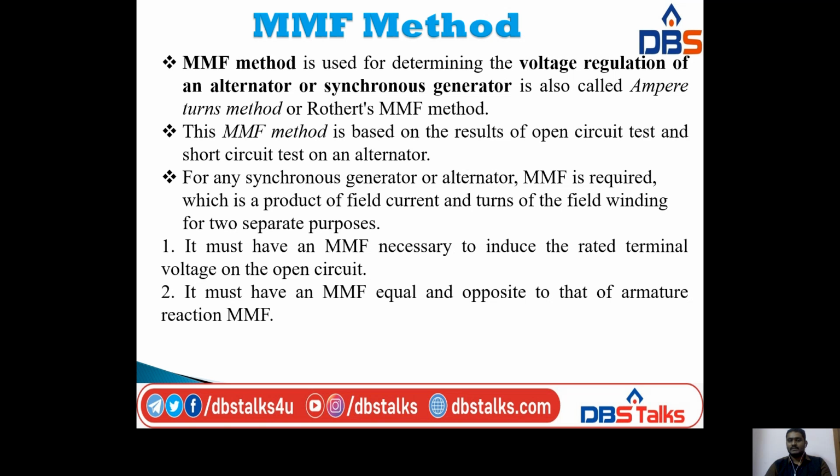Firstly, it must have an MMF necessary to induce the rated terminal voltage on open circuit. Next, it must have an MMF equal and opposite to that of the armature reaction MMF.